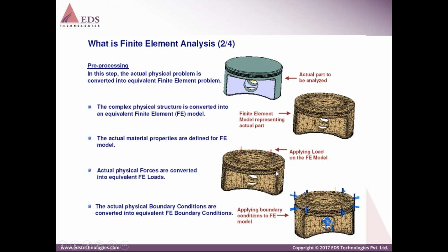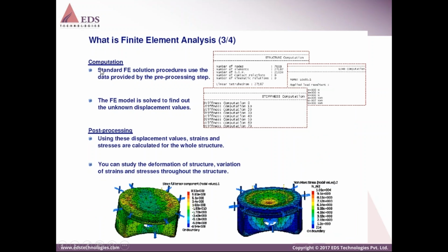Then the loads will be applied to that finite element model. After applying the loads, we'll apply the restraints, whatever the boundary conditions and restraints are there. So they will be applied, and this model is given for solving. That is the computation step. So the software will solve it and give some numerical results.